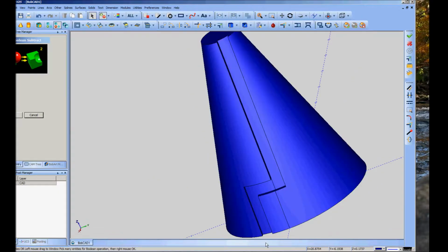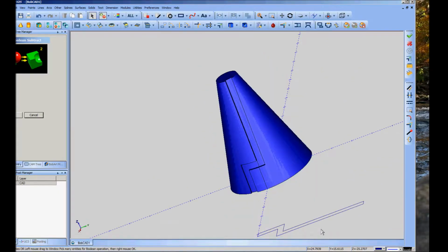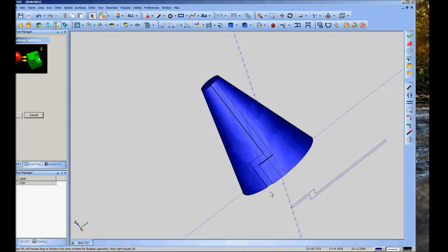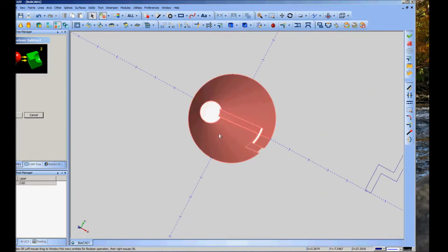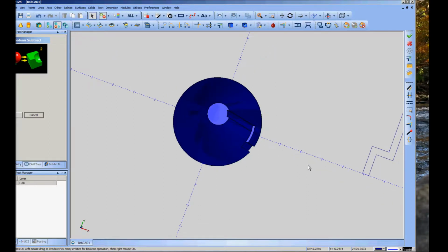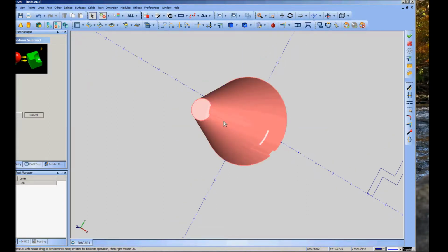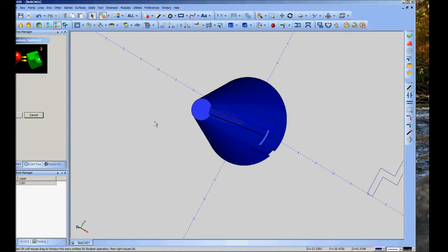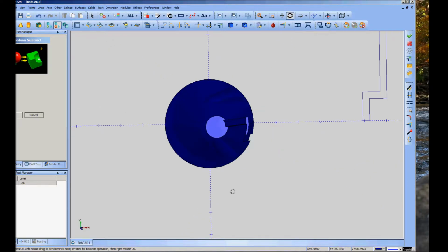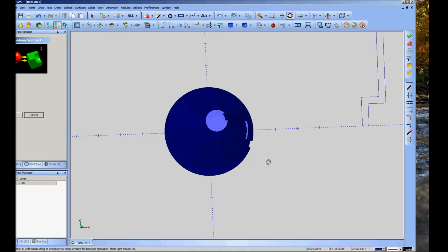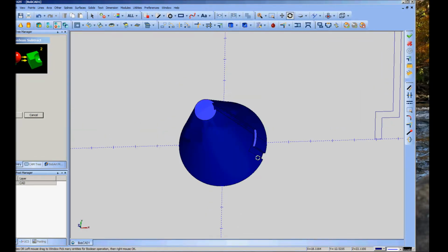Now, there are certain things that are endemic to this shape that the person wanted, which is that one of these is off-center. One of them is off-center one way and one's off-center the other, actually. If you wanted to be a little bit more precise and get these all lined up directly radial to the cone, you'd want to do it in 3 different shapes. So it would get a little bit more tricky there.